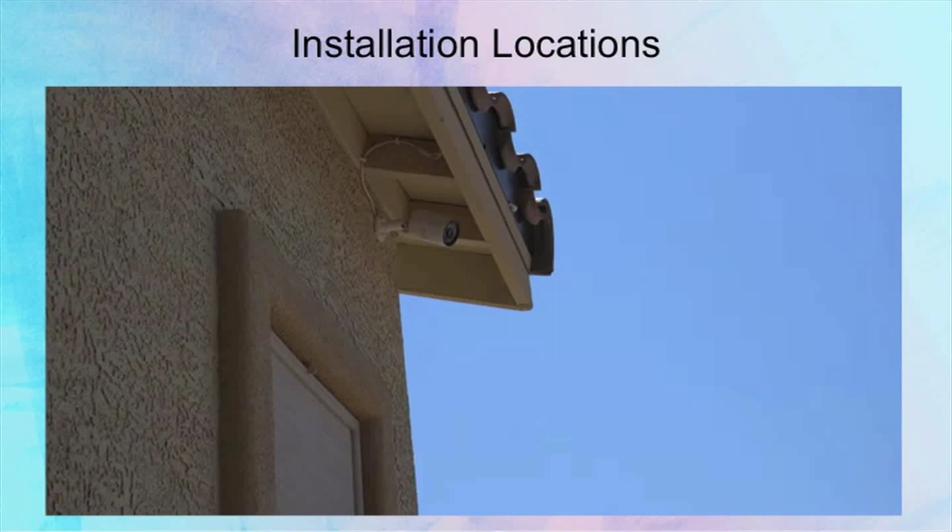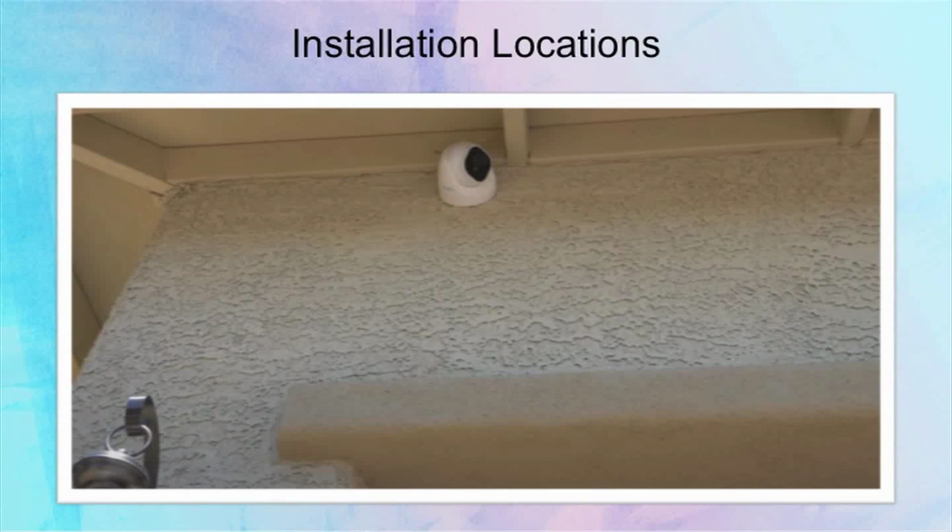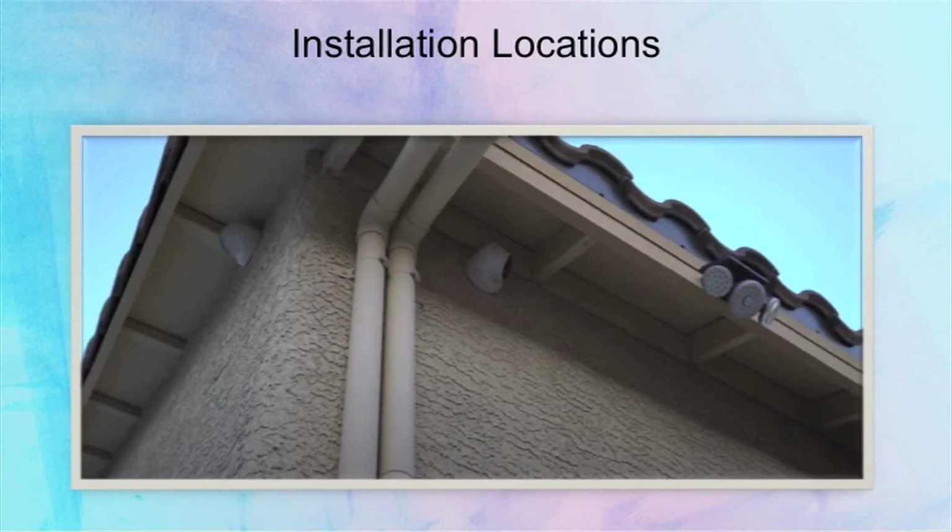Depending on the installation locations, the area that is to be covered, the number of CCTV cameras to be installed, and the wiring or connections from the CCTV cameras to the central location where the screen of the CCTV camera view will be installed will depend. Depending on the requirement of a wide angle view as well as the clarity of the area to be covered, the installation locations are chosen. Also, care must be taken that the cameras are not installed in locations where they are liable to be damaged due to various environmental and external conditions.